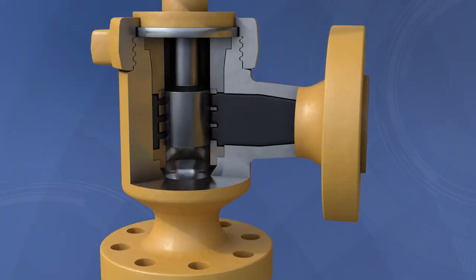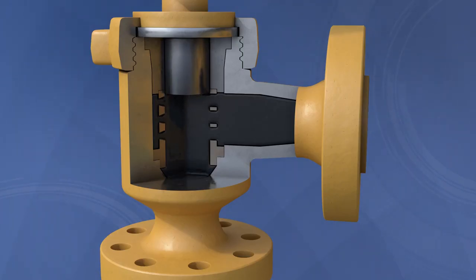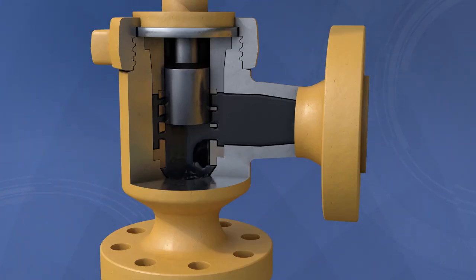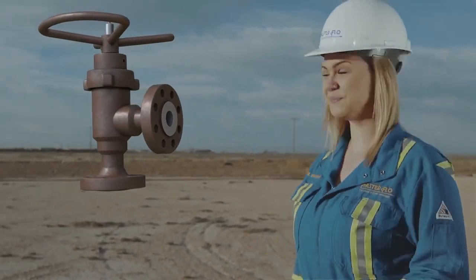The cage and plug choke valves work best when the cage ports are fully open, which allows the high-velocity jets to be perpendicular to the valve axis. Otherwise, the jets are directed towards the valve outlet and cause its erosion over time. Let's move on to the most advanced choke valve, the cage with external sleeve.